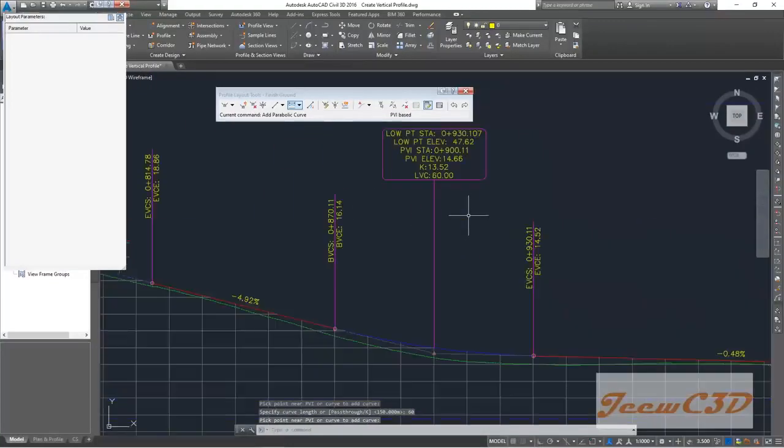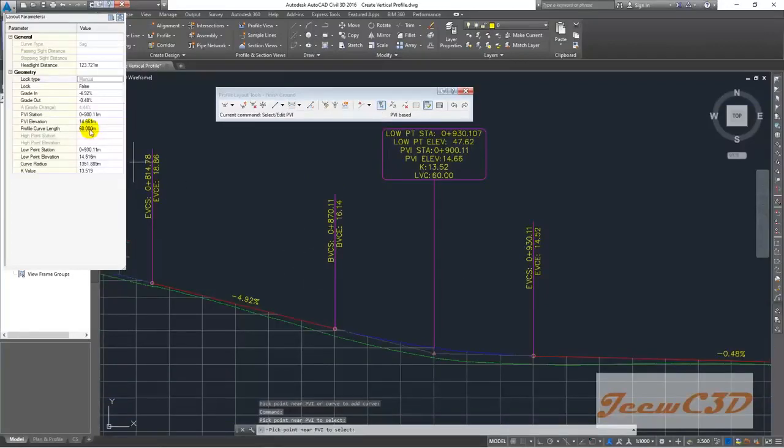You will see now still that is not satisfied. I have to increase the curve length. I increase my curve length up to 70 and see, still not 80, okay. Now instead of increasing the curve length, you can decrease the gradients and see what happens also, because if you decrease or increase the gradient, these values will be changed.